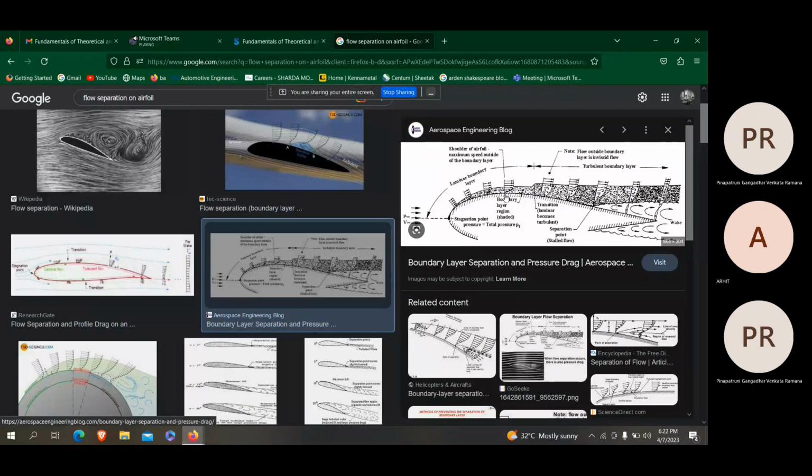Another thing you have is a pitot probe, placed just 3 mm above the wall surface. They have placed another pitot probe exactly at the same static port location, where we have drilled the hole, but 3 mm above it. Okay, sir, got it.